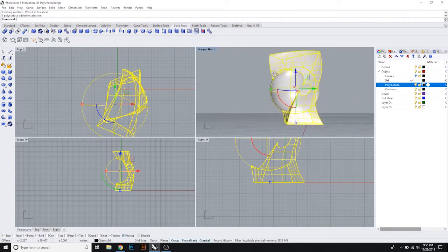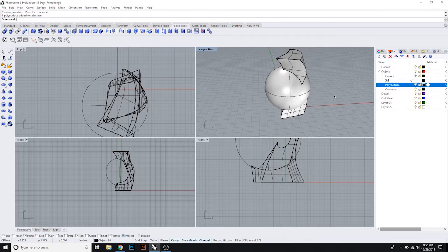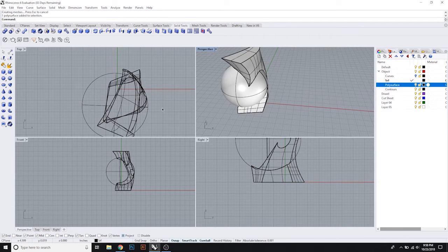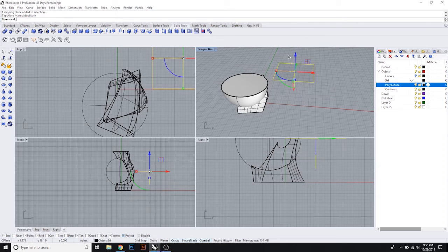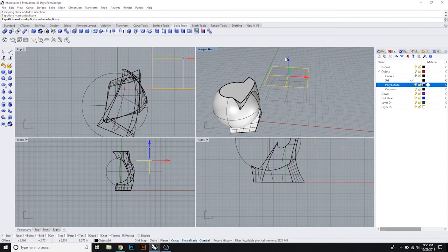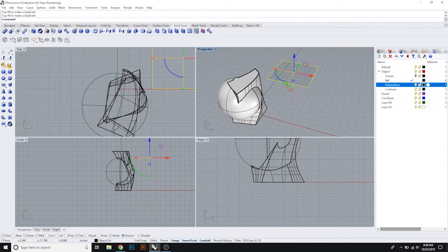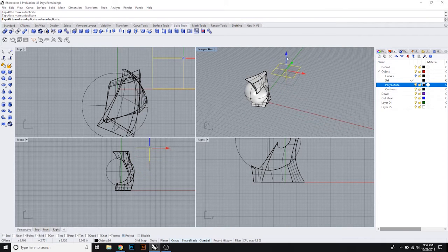So what this does is combine the two shapes. So to check, when I bring my clipping plane up, as I move this up, I don't have any overlapping volumes. So all of my cuts are going to be closed surfaces. So that's important.